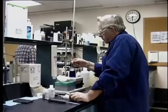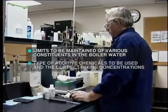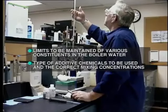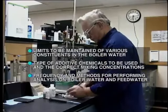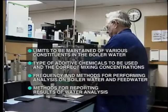Clearly, from our discussion here, we can see that boiler water conditioning is often a compromise, and it does require experienced water treatment specialists to establish the procedures for your particular boiler. Now, this will include the limits to be maintained of various constituents in boiler water, the type of additive chemicals to be used, and the correct mixing concentrations, the frequency and methods for performing analysis on boiler water and feed water, and the methods for reporting results of water analysis.